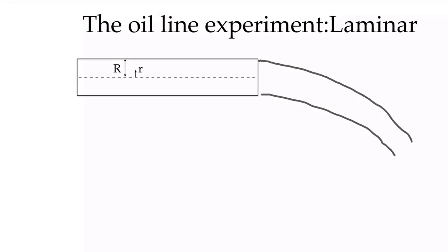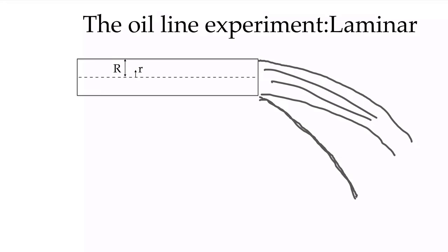But what we also see is that there's a secondary stream that falls more quickly. So this is the main flow, and then there's another stream that falls here, and it's connected by a web between here, so a very thin film of oil between those two. And we can see what's happening here by thinking about that laminar velocity profile. We had a nice parabolic velocity profile where the center line velocity was 2 times the average velocity,